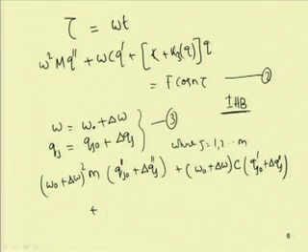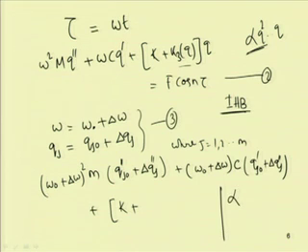Similarly, for this term I can substitute. This will be k plus k q. If I take a Duffing type of equation, in this case it will be alpha q squared into q. So this q squared term I can substitute with q equal to q j 0 plus delta q j, squared, and in addition I have to multiply with this q. So it will be alpha into q squared q, that is q cubed. So it will be alpha into q j 0 plus delta q j whole cubed.